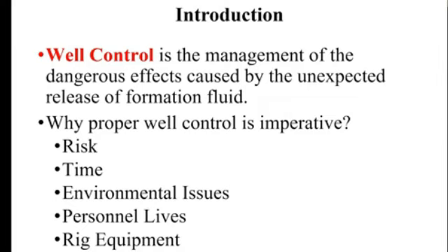There is a difference between a kick and blowout. Obviously, the kick is when formation fluid starts entering the wellbore, and we can have control over the situation, and we can manage the formation fluid which is entering the wellbore. However, if for any reason we lose the control over the operation and formation fluid reaches the surface in an uncontrolled manner, then this becomes a blowout. Obviously, blowout is much more costly and much more dangerous than kick.